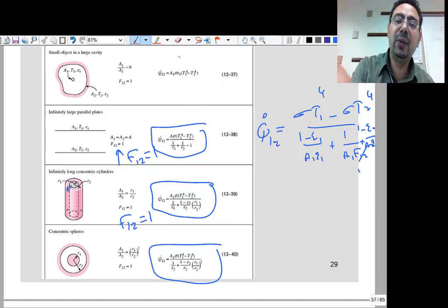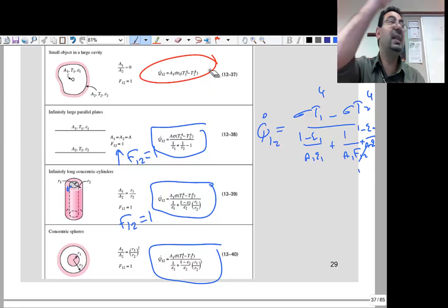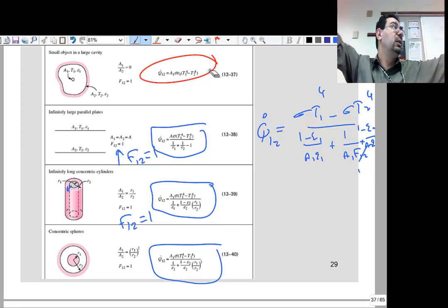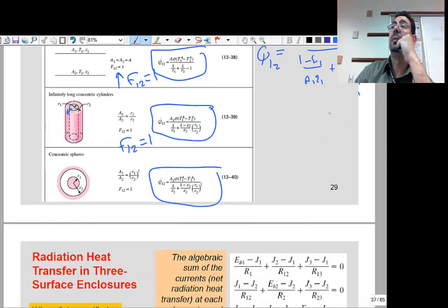This is basically a surface that's very small compared to its surroundings. So the bulb of the thermometer is very tiny compared to the duct, or the room, or the furnace, or the place where it's inserted. So that's why the equation is area sigma epsilon T minus T. Your area times your epsilon. Right?